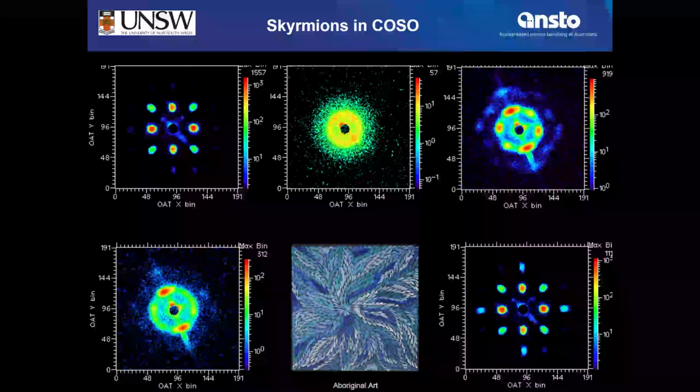That skyrmion data bit would be still much smaller than the domain walls in a current computer hard drive. There must be a certain spacing between the domain walls, otherwise the magnetic bits depolarize each other. The skyrmion is much smaller in size, so it would increase the data storage capacity tremendously.